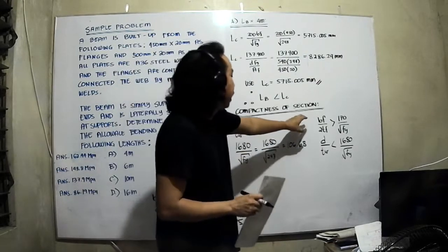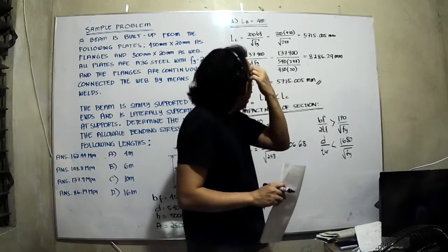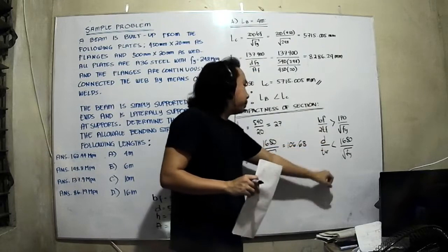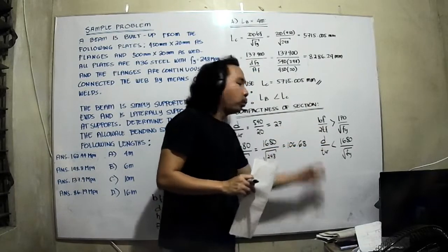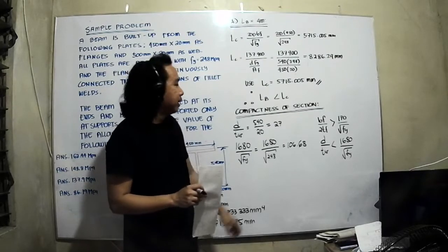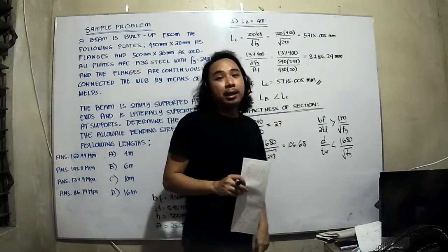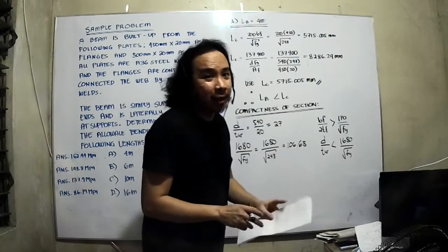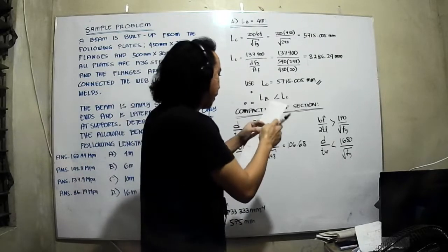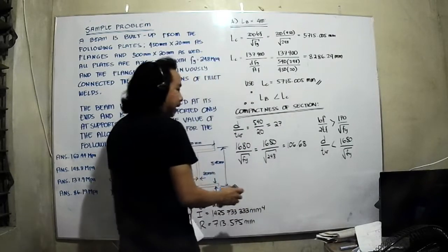We already know the section is non-compact, because that condition on its own is not enough to satisfy compactness. Half is still not enough to satisfy the condition of compactness. So it is non-compact. We just look at where it falls when compared to 250. I'll just erase this part.